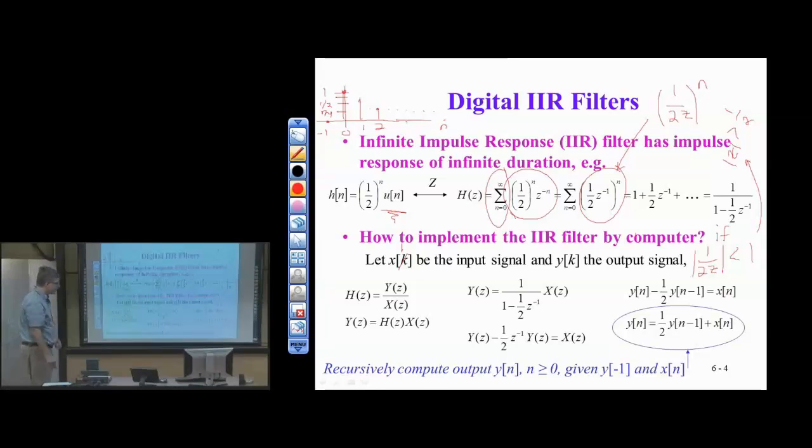And again, the transfer function assumes a linear time invariant system for this to make sense, to get the ratio of the output z-transform over the input z-transform. If the initial conditions were not 0, we could not get this ratio. So we multiply both sides by X of z, and we get a very familiar form: the output z-transform is the input z-transform multiplied by the transfer function of the LTI system. We can now substitute in capital H of z directly into the formula, and now we're very close to the final answer.